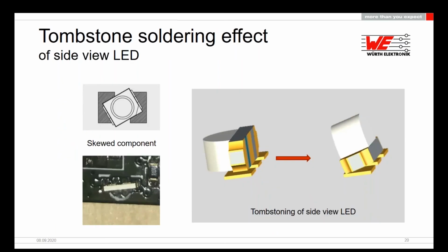Side view LED is different from usual electronic components. With the side view LED, it happens after soldering that the side view LED is often skewed or lifted up like the top mode. This is the common tombstoning effect by side view LED.